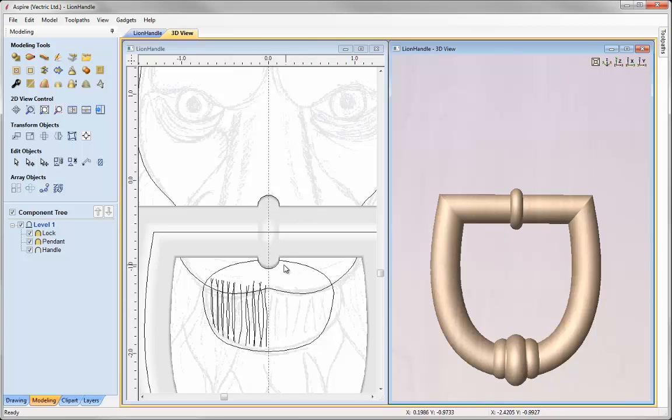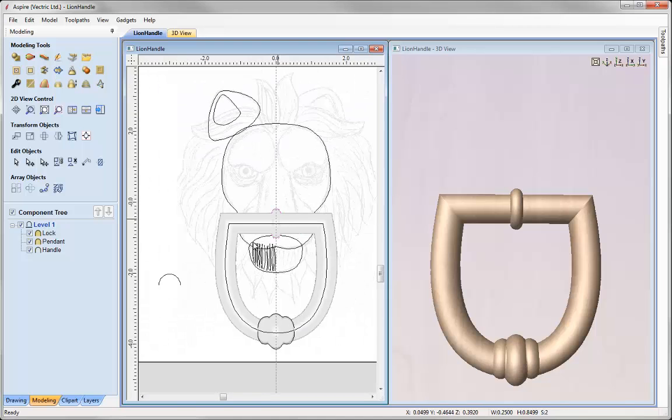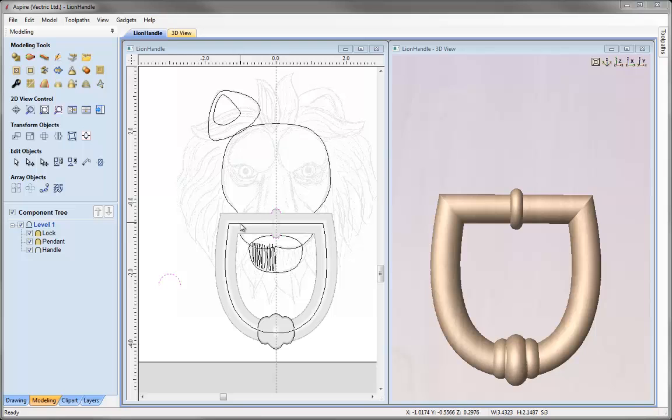So what I need to do there is take these vectors here, and I also need to take this cross-section vector here, and I'm going to copy these vectors over to the base shapefile along with the face shapefile in order for us to get the correct recessed version of this shape for when we model that recessed shape that houses the handle in place. So this will become more apparent later on when we come to model the base shapes along with the face shapes. So let's just right mouse click and press copy here.